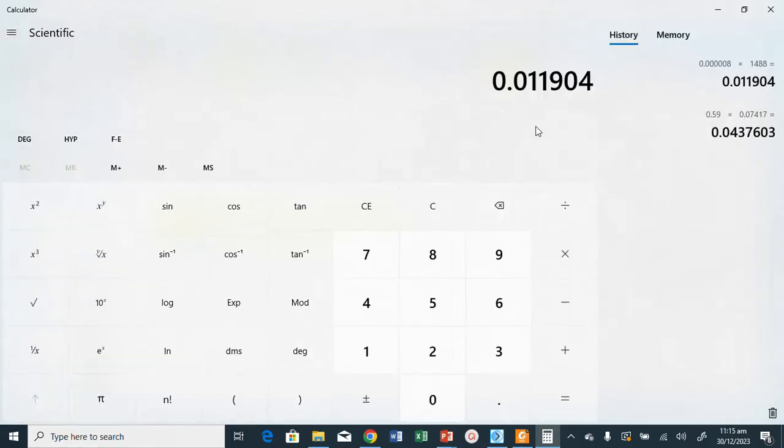So now we have 1,200 minus 14.696, because that is the atmospheric pressure, the base pressure of this software. Although the base pressure they gave us is 14.7, 14.696 is the base pressure of this software. So that is what we're going to use. We enter. So this is the value we got. So now we are going to input this value.